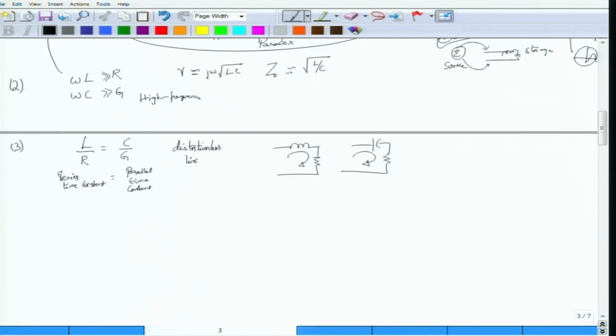What do we mean by this is that if you launch a particular waveform on the transmission line at, say, z equal to 0, which corresponds to your source, then at z equal to L, which corresponds to your load, the waveform would be delayed, of course, because it is a transmission line. Its amplitude might also decay, indicating that the attenuation is not 0, but the waveform actually would be the same. So you can see some delay, you can see some amplitude loss, but you will see that the waveform actually has not changed its shape.